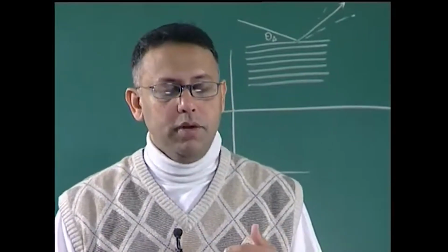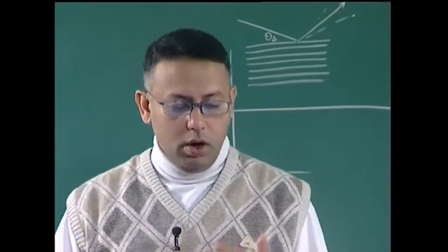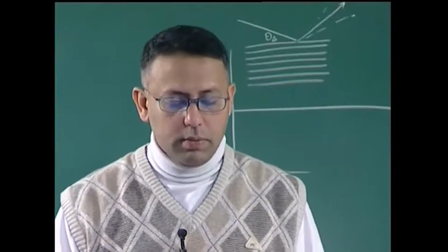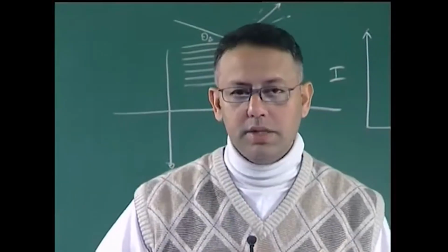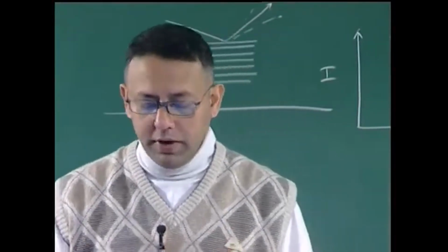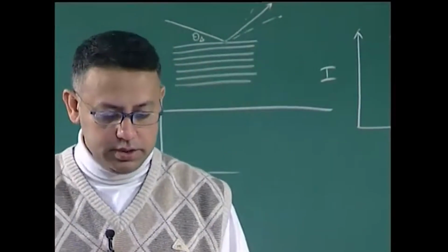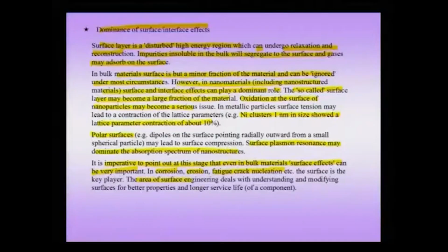And if there is a way of suppressing or reducing the steps, intrusions and protrusions which are produced during fatigue testing, then the fatigue life of the component can be increased. The area of surface engineering deals with understanding and modifying surfaces for better properties and longer surface life, and surface engineering, as you can clearly see, is going to play a much more important role when you are talking about nanomaterials and nanostructures.